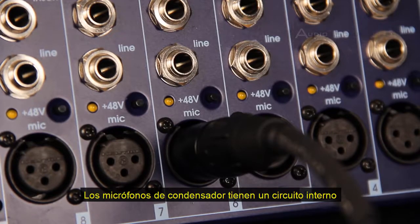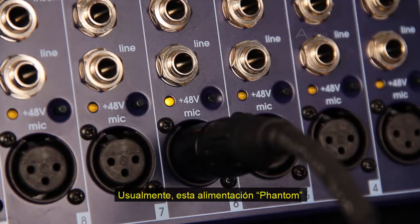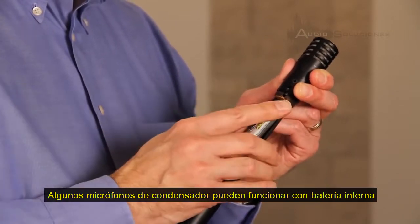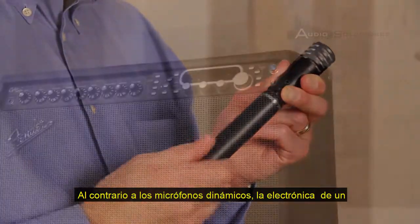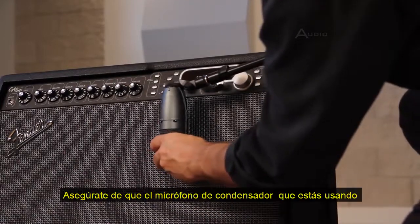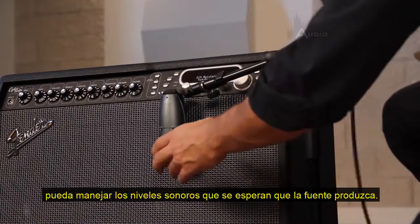Condenser microphones have internal circuitry that requires power to operate. Usually, phantom power is supplied through the microphone cable from the mixer or recorder. Some condenser microphones can run on an internal battery, but that's less common. Unlike dynamic mics, the electronics in a condenser mic can overload when exposed to very loud sounds. Make sure that the condenser mic you're using can handle the sound levels that the source can be expected to produce.